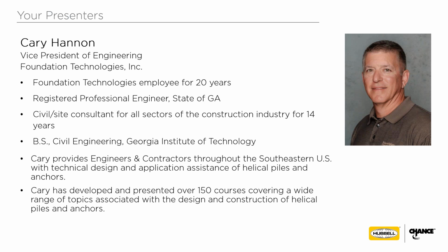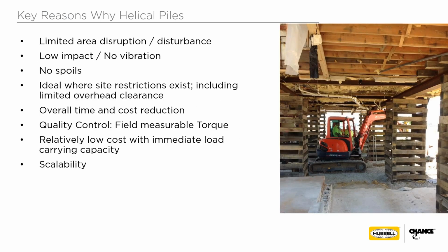All right, thanks, Kerry. So why do we use helical piles? Key reasons: limited air disruption. I'll go through some of these bullet points, not necessarily all of them. No spoils. Helical piles are a displacement pile method, which means that we're not digging and removing any materials, if you're not overly familiar with helical piles.